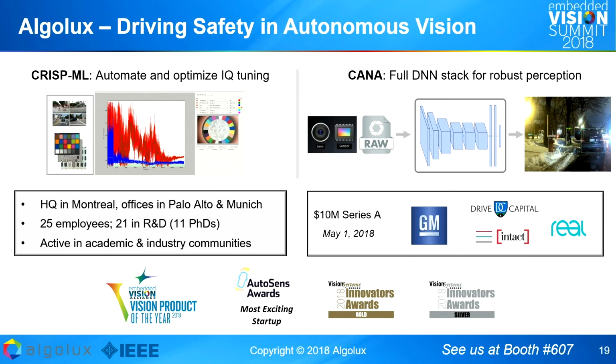But that said, we can certainly model the effect of certain capture parameters. For example, HDR fusion is a good example where we can fairly easily model the effect of what exposure settings you use, how many exposures you use, how you fuse them, on things like contrast detection probabilities. That's possible. So HDR or WDR is one of the key parameters. That one you really have to take care of because it's so essential in the automotive context, and that is very accurately modeled.